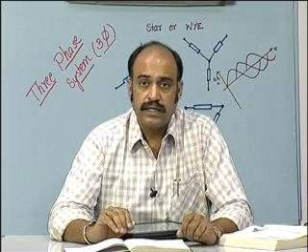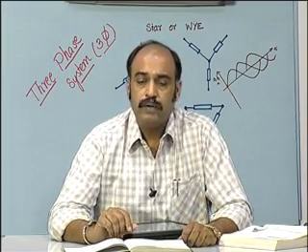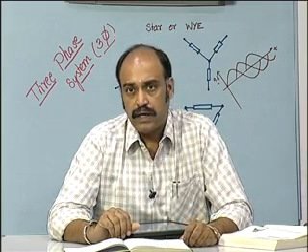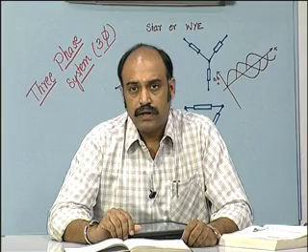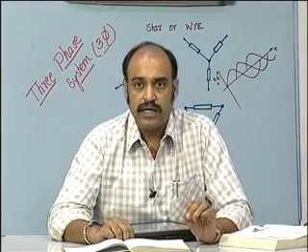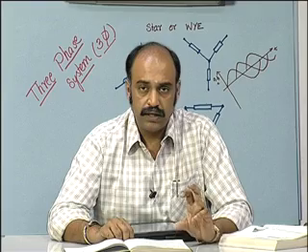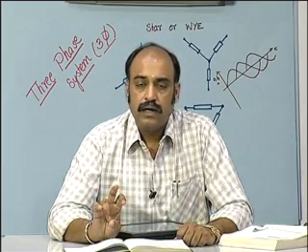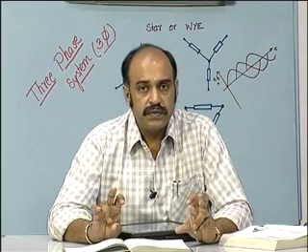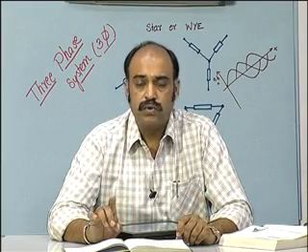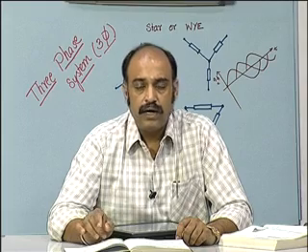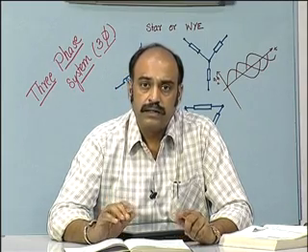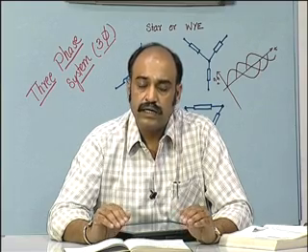In the case of the delta circuit, we discussed one important unbalanced load condition, and that is, in the extremity, if we had just one single resistor as a load. Then two of the lines will have currents in them, that is, one will have a forward current and one will have the return path current of the resistive load. The third line will not have any current and it will be just open.